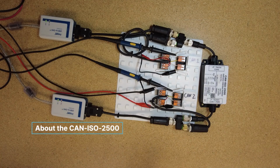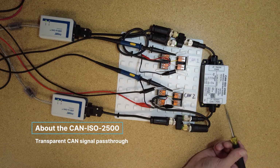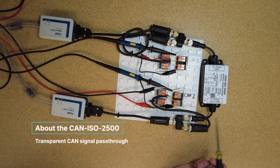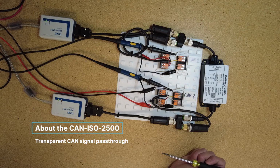So a little bit about our CAN isolator. It is a transparent device where CAN signals can pass through very quickly and very easily. The advantage of this is you can pass CAN signals between two different devices that are on the same network but powered by different power supplies. So this is important in like battery electric vehicle applications, sensitive measurement applications, and things like that.